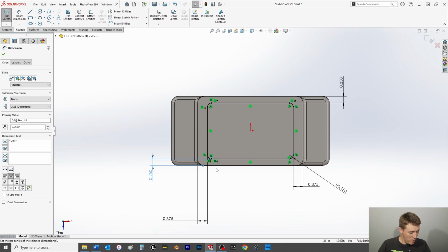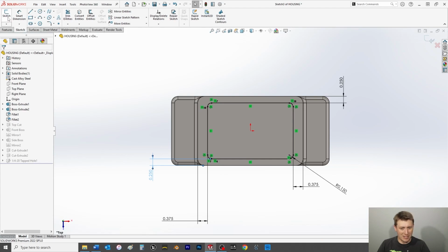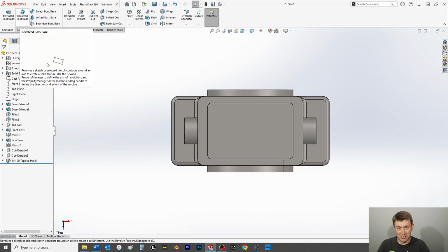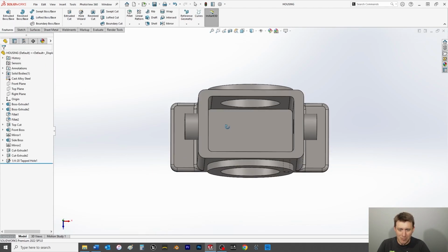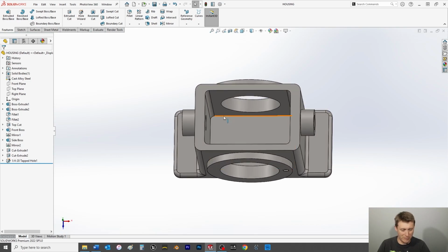Now, section 2.49, there are two things to keep in mind. We can now exit out of the sketch, up here, top left, or we can rebuild the sketch, which is this little traffic light icon up here in the top middle. But for this particular situation, I'm just going to exit the sketch, and then in the next example, I'm going to show you where rebuild may come in handy. So we'll simply exit the sketch, Control S, save often, and now I'm going to tilt the model a little bit for a better view here.